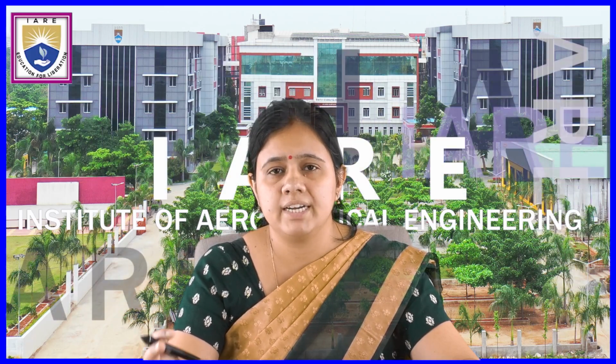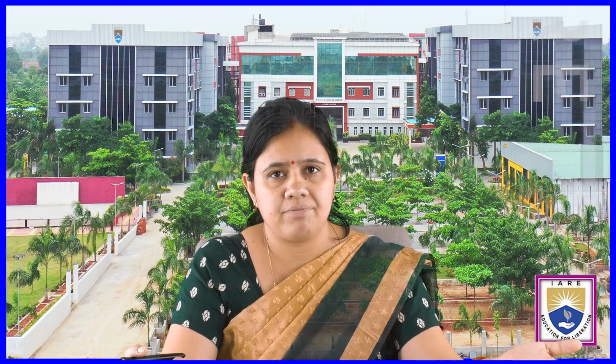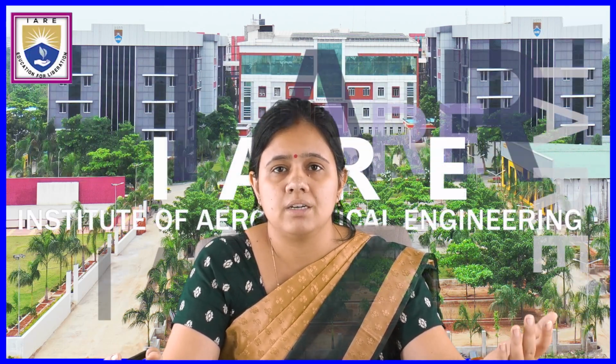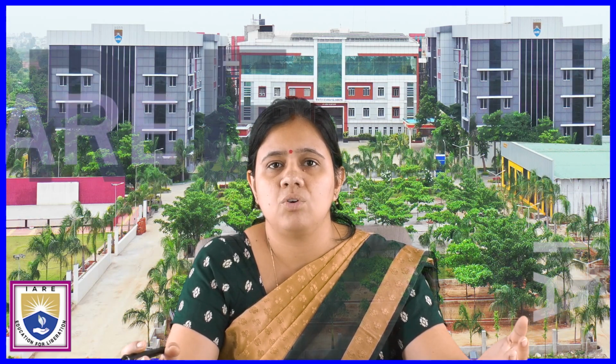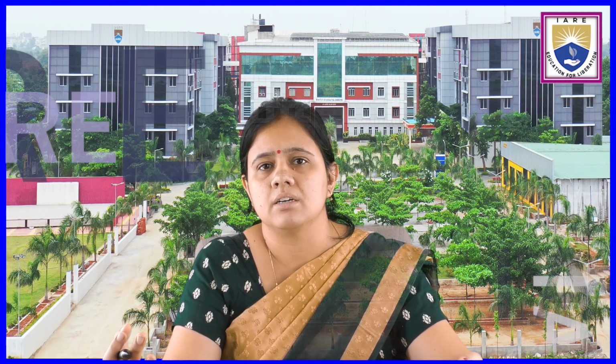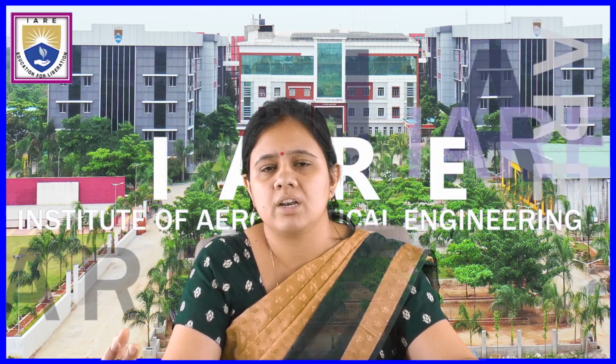We get the analysis like this: if you are going for a smaller area, up to 10 kilometers, then the haul container system will be effective. But if the path is more than 20 kilometers, then the stationary collection system will be better for the collection of garbage and hauling to the MRF location site. This was the problem statement that we solved to know the actual analysis of the haul container system.